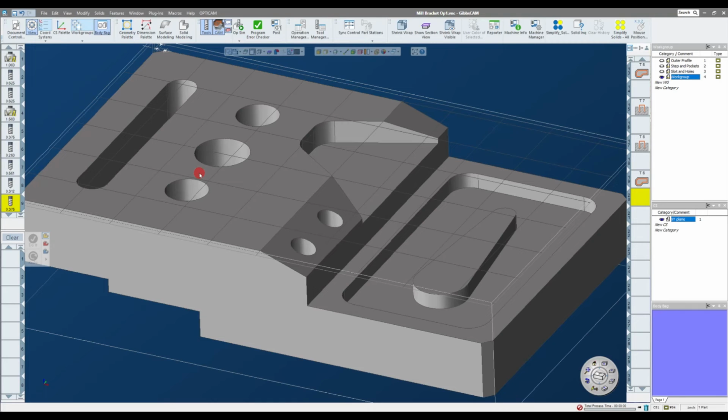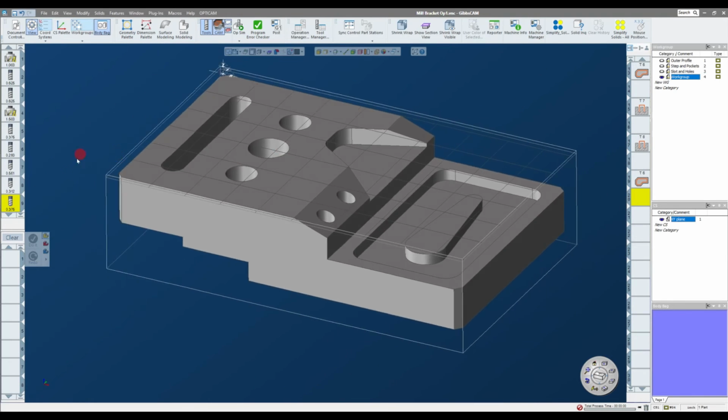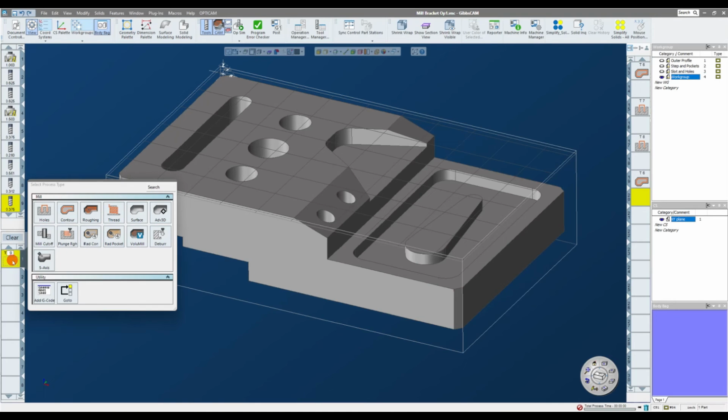Now for this, I'm going to show you a simple way to do this, and then I'm going to show you a bit more of a detailed way, which involves a bit of solid modeling and a bit of model modification, which is going to give you a bit better tool path. So if I bring this tool down, and if you have the option for solid surfacer,